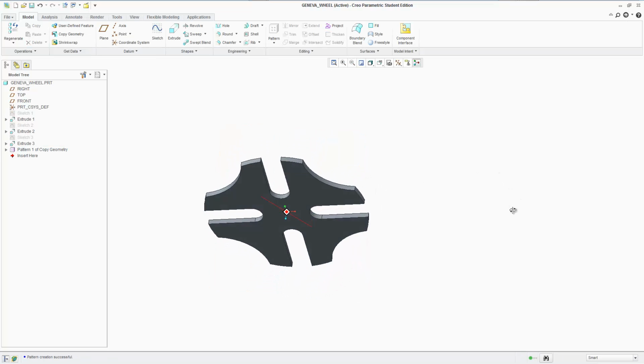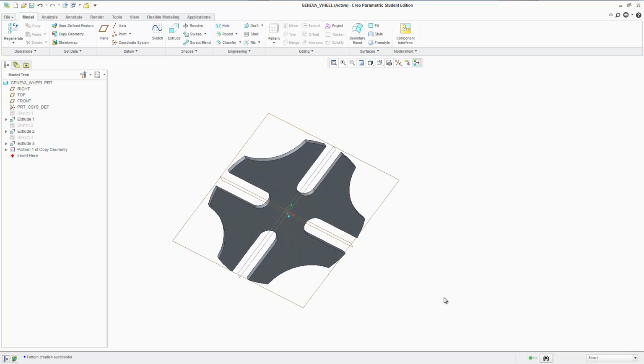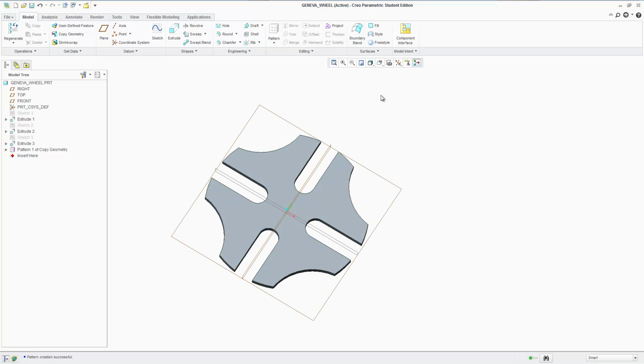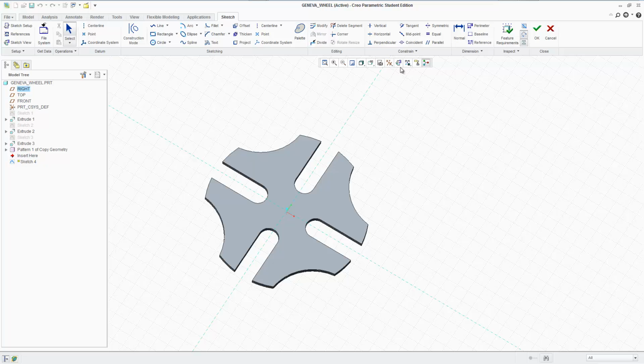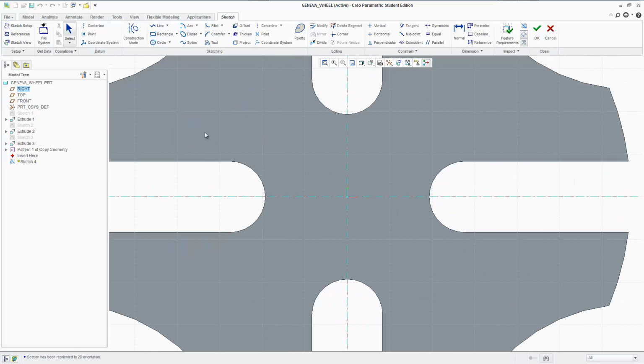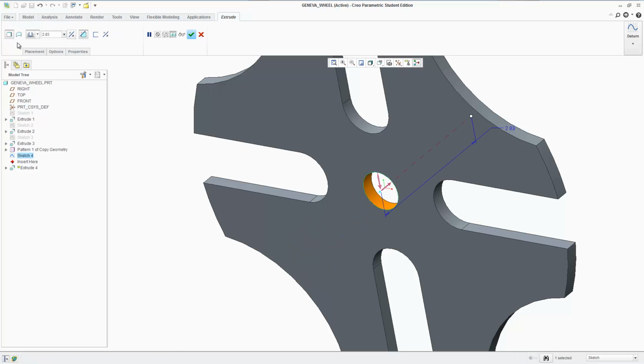So right there we have our Geneva wheel made, and it looks pretty nice. I think it looks nice, at least. That's it. And of course, any wheel, we're going to have to have a center hole punched in, and we're going to punch a hole in the center. Let's go here. This is where you would have your motor plugged in. Well, not really. You would have just a shaft plugged in that will allow the whole thing to rotate. Let's make that diameter 0.475. Remove material.